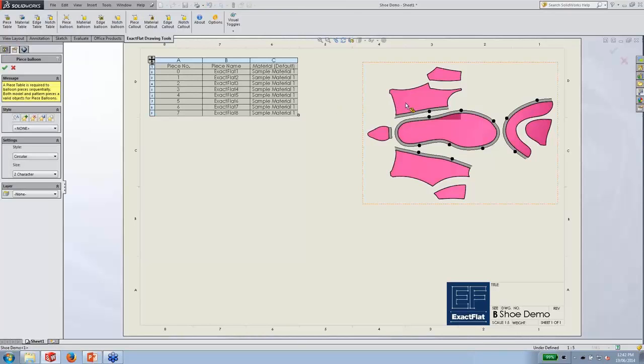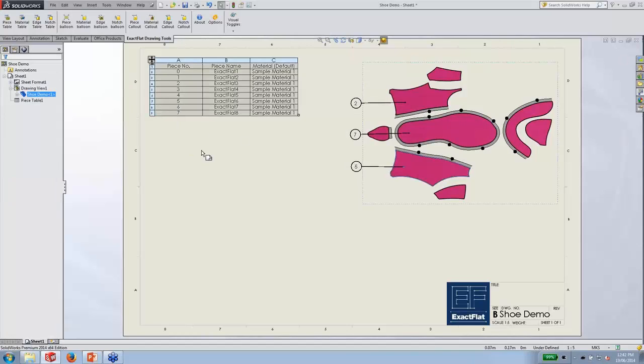This is particularly useful if you're making products that have very similar pieces. So for example, for a lot of composite parts, they may have pieces which are very similar in size. They may be off by 1/4 of an inch or 1/2 an inch or things like that, and it's difficult to know which piece is which. Well, this is a way that you can help your assemblers and your sewers and your layup technicians to very quickly identify the pieces that are part of their task list.